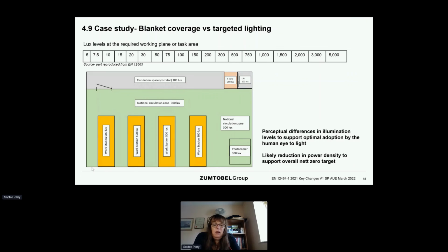And if the client phoned you up, say, in a year's time and said, we have some people now using the space that have visual acuity problems, we need a higher lighting level for them, you could either introduce a table lamp or a freestander at that workstation for the affected people, or you could just set a third lighting scene to, say, 3 or 4 luminaires over one workbench, and turn them to 100% at the 750 lux you built in reserve.